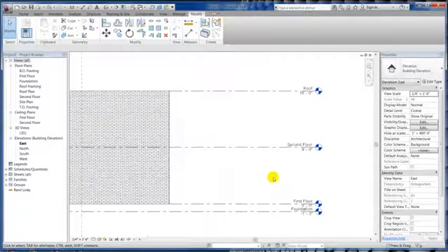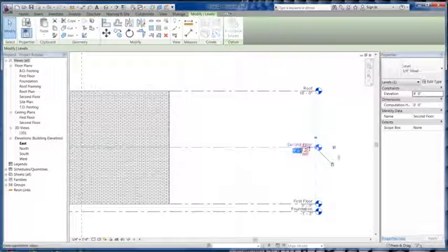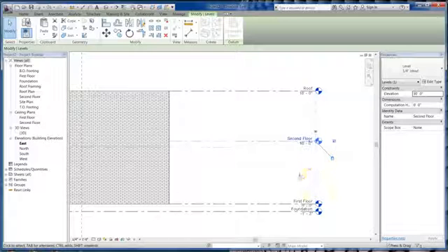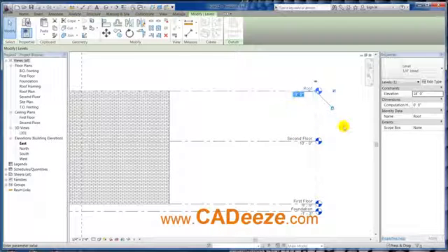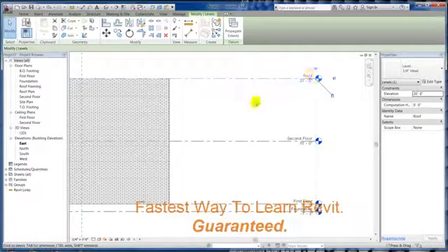Now, if I wanted to have 10-foot ceilings, I can come in here and edit this to be 10 foot. And then I want to do some math in my head. Say I wanted a 10-foot second floor. That would be 20 foot, right? So you go 20 feet and boom, and you notice that my wall stretched up with my roof level.